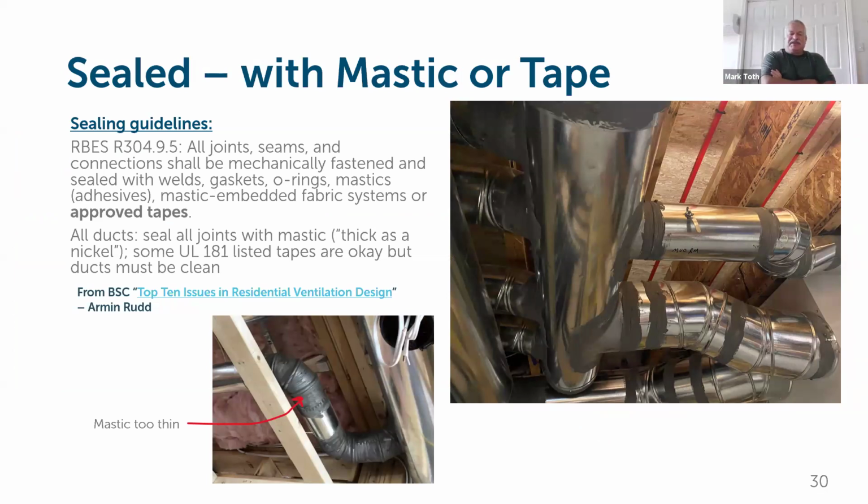You have to seal the ductwork, because if you're not sealing the ductwork, whether it's intake or exhaust, you don't really know where the air is going. There are different ways to seal duct. You can use mastic, you can use mastic tape, you can use the metal tape. You do not want to use regular old duct tape. It just doesn't last. Regular old silver duct tape will look great today when you leave the job, but 6, 8, 10 months, a few years later, it's going to fall off. So we want to use a very high quality tape or the mastic sealant that you paint on.